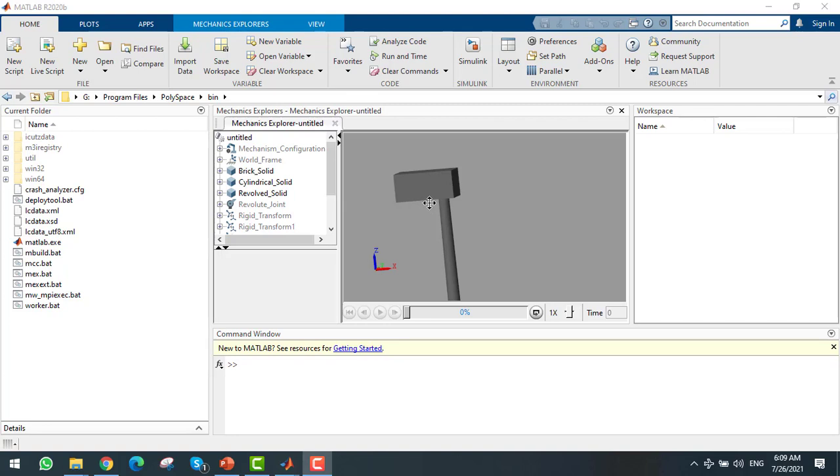Or we can use some other CAD software and import the resultant step file from them into the Simscape and use it there. So I've actually done that. I've downloaded a very beautiful airfoil from GrabCAD as a step file, and I used it in this project. You can do the same as what I've done, or just design it by yourself.